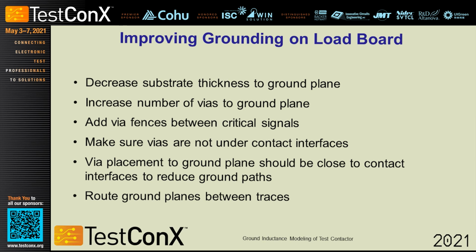Also, one thing I found from laying out a lot of boards, you want to basically route the highest frequency signal first, and you want to route that as the most direct path, and then work your way down as you go lower in frequency, routing the board out that way. Then the DC signals and stuff like that are last, and they can hopefully avoid all the RF signals that are pretty much direct paths, if you can make them direct paths.